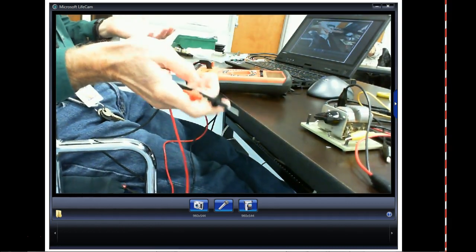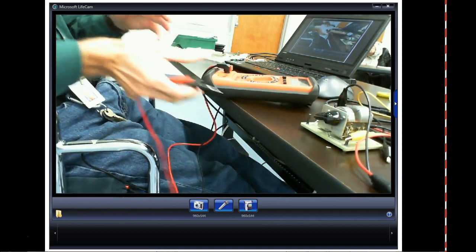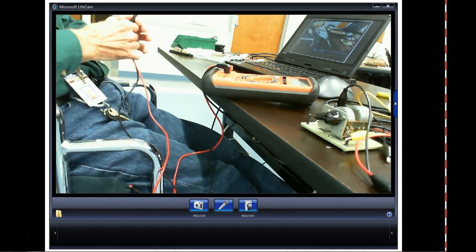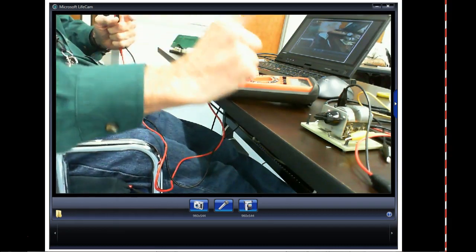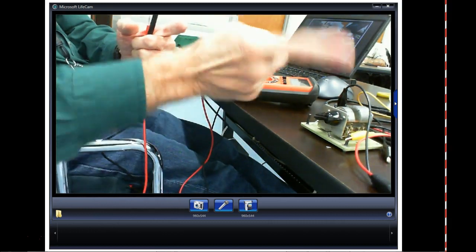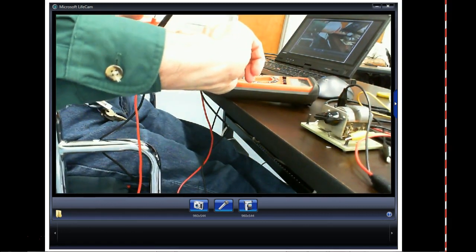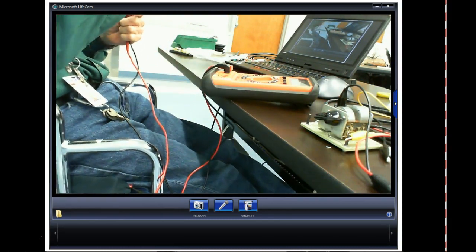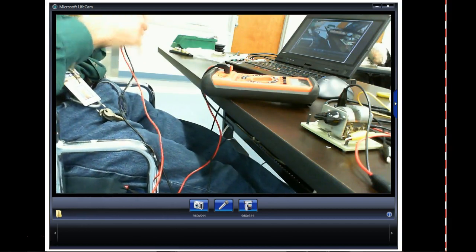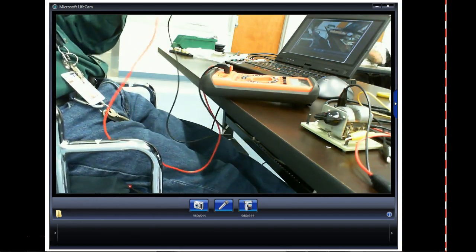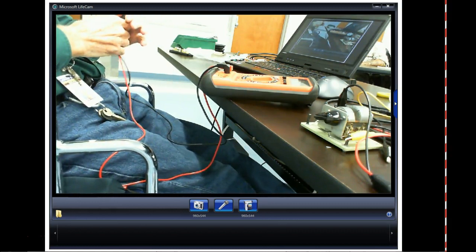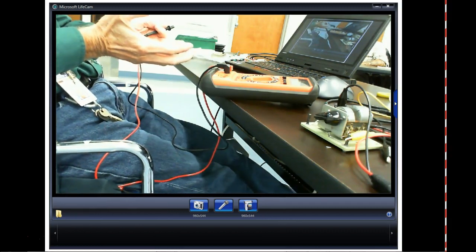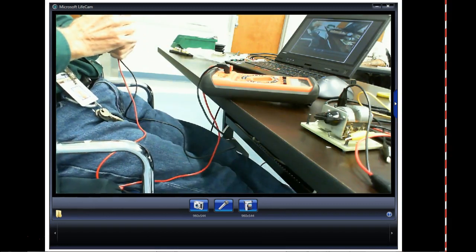What that means is in a DC circuit, we had to really honor polarities because on an analog meter, you had a pointer dial on it. If you hooked it in backwards, the pointer would peg out against a stop, and it could bend your dial because it's really thin to get a real accurate reading. And if you bend it, your meter is reading one thing and your scale is reading another, right? But when we came out with digital meters, they measure negative voltage just as well as they measure positive voltage.